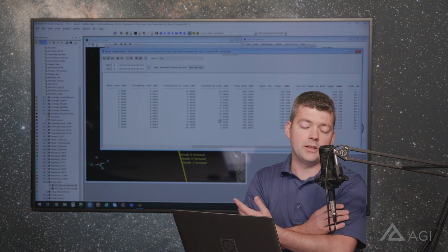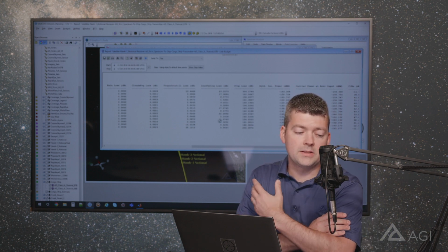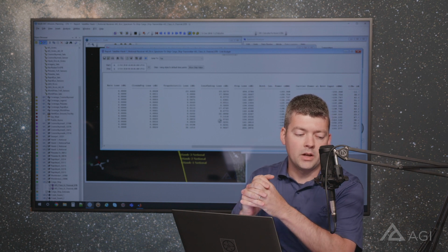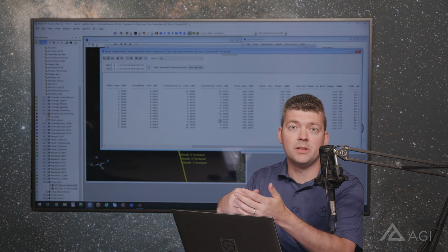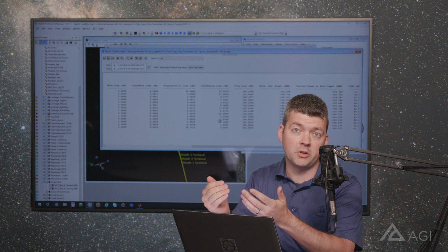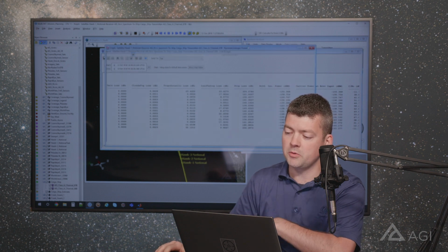So what's actually happening is that we've turned on the ITU provided model for ionospheric fading. And what it's telling us essentially is that at this frequency, we can expect to see some very large, rapid, and chaotic changes and unpredictable fluctuations really in our signal strength. So that's what these steep drop-offs are actually representing for us.